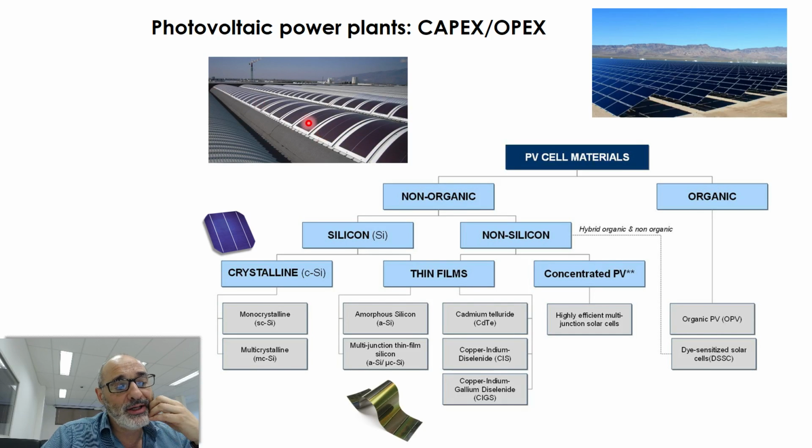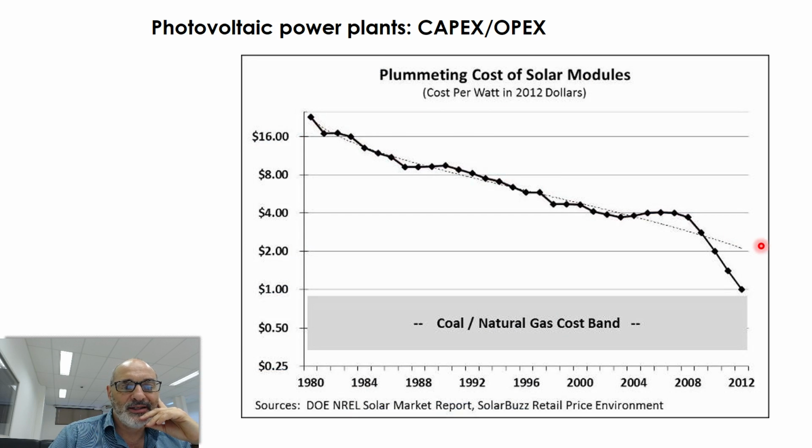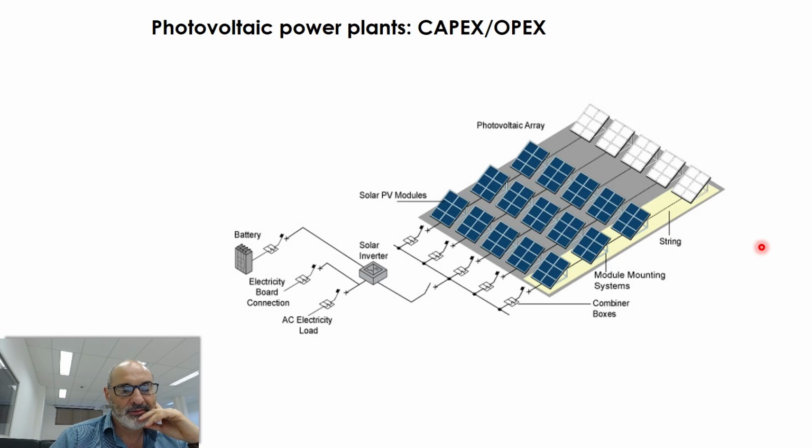So here you use the roof's structure to support the panels. They are flexible, they are resistant, so you don't have to worry about the structure. But for these materials that are more fragile, you have to worry about the supporting frame of these panels. So those are the types of decisions that you have to make. Are you going to buy this type of panels or these type of panels? You also have panels that track the movement of the sun. They are more expensive, but they are more efficient in compensation. Also, the price is decreasing over time because of scale effects.